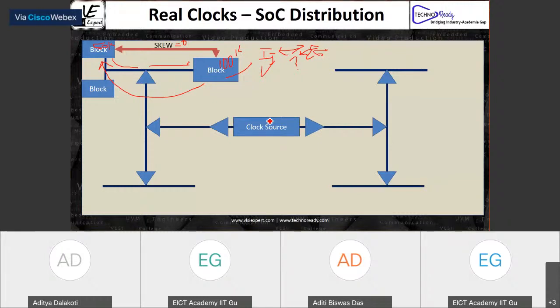Absolutely, power and area. Maintaining H trees and skew costs us a lot of power. And if you actually work out numbers, it grows exponentially here. So you tend to at some point give up that exponential basically.